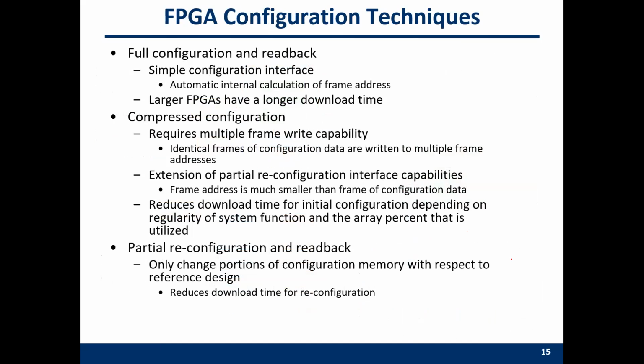Sometimes the configuration of an FPGA can be very large. You can naively read it directly from some memories, but you need to pay a longer download time, or you can do some compression. So you need to uncompress the data at runtime, and then write these uncompressed data into the configuration memories.